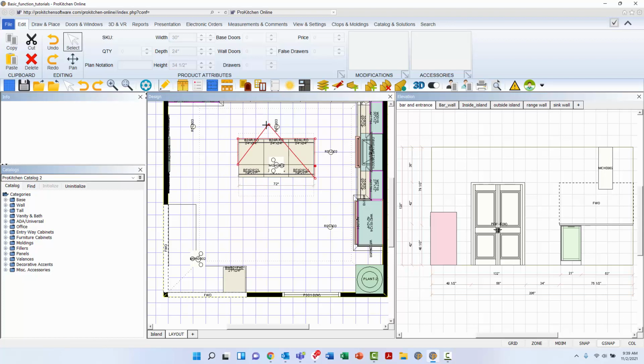If, when moving a point, you end up crossing one line with another, creating an unrealistic shape to the countertop, you may hover over either of the two lines, right-click to open the subset of tools, and select Intersect. This will remove the intersection of the two lines at the cross point